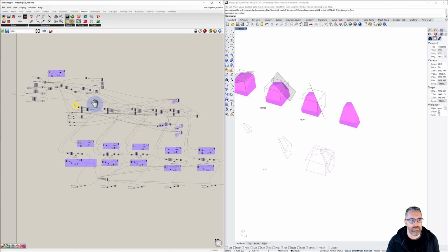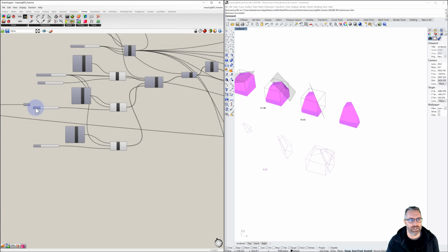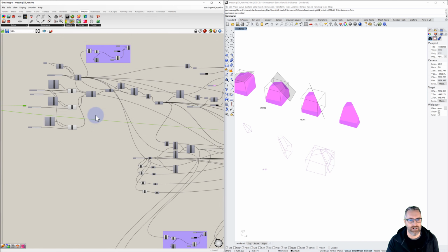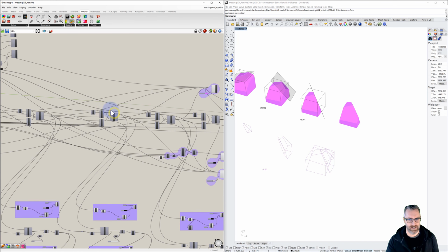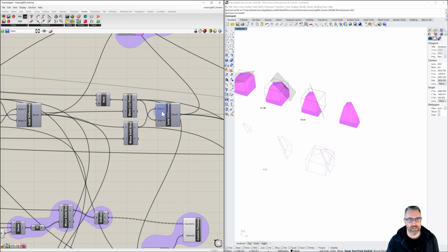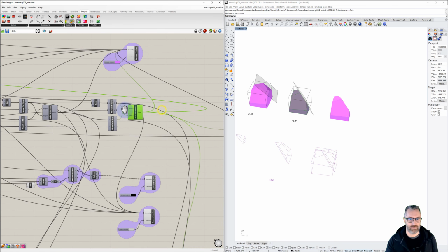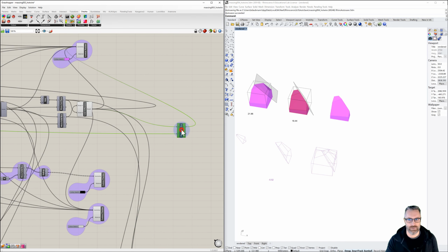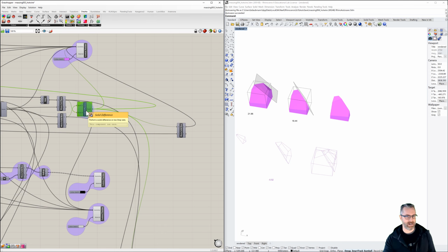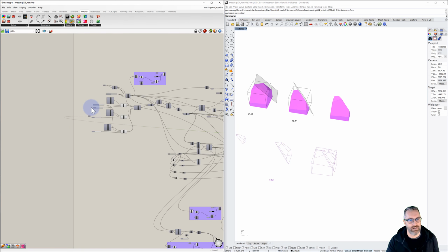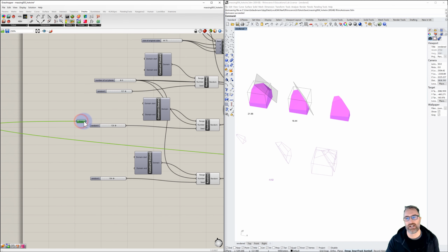The other thing that I've done on the Grasshopper side is I've made a BREP container, which connects all the way back from the final outputted geometry in our string. I guess we have a moved option there. Then I just connected a BREP container to this. If I hide this, that BREP container comes all the way back to the beginning. The reason I did that is that I can just bake from here.